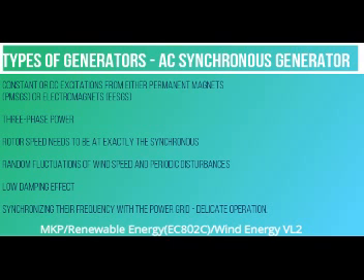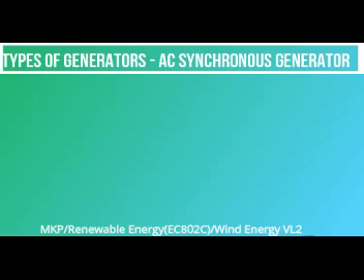Moreover, synchronous WTGs tend to have a low damping effect so that they do not allow drivetrain transients to be absorbed electrically. When synchronous WTGs are integrated into the power grid, synchronizing their frequency with the grid requires a delicate operation. In addition, these generators are more complex, costly, and prone to failure compared to induction generators.